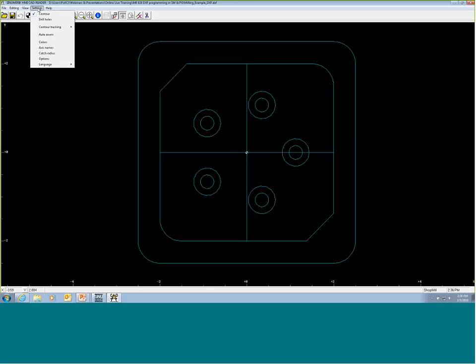So under settings, I do need to pay attention to what I have picked here, contour or drilled holes, because the display will change too. If I know I'm going to pick some holes here, I do want to make sure I've pre-selected the drill hole feature. If I want to do a physical contour or shape, it'll give me the appropriate contour buttons, but I do need to have the settings set up for that. So that's something you bounce back and forth from quite a bit, especially if you know you're picking holes at some point.